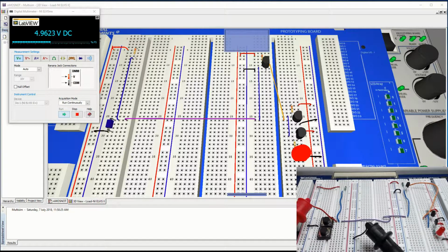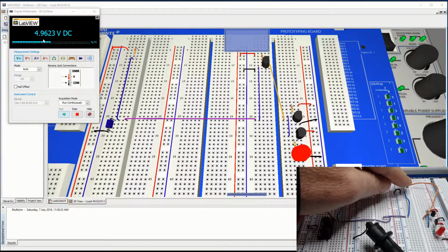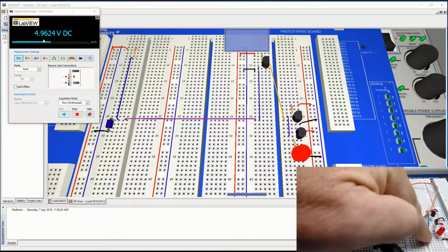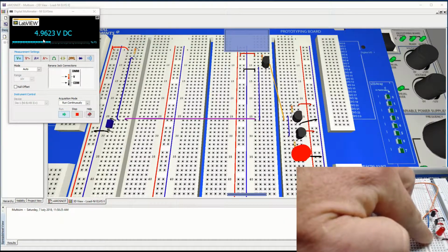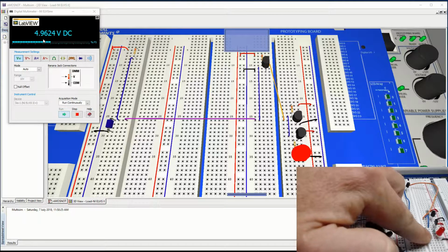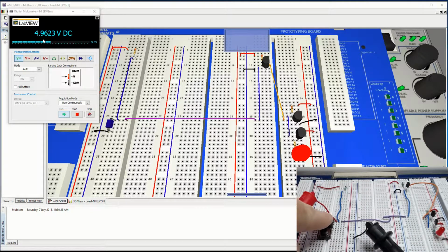Right, everything's done now. So we've got our multimeter connected to the gate A. When the button is not pressed, we're applying 5 volts at the gate of the nMOS. And then we drive our circuit, and as you can see, the NOT of 1 equals 0. When we press a button, we're applying virtually 0 volts at the gate, and this equates to a NOT of 0, which is 1, so the LED is on.